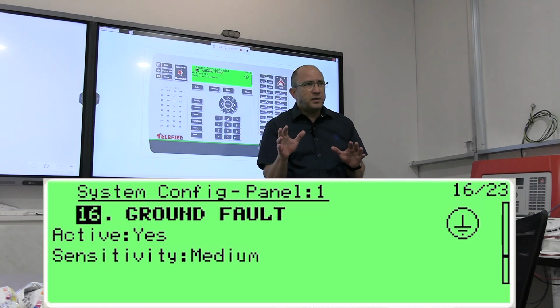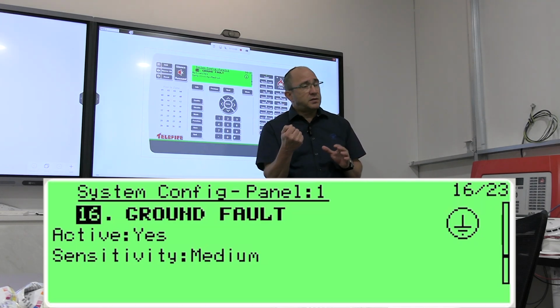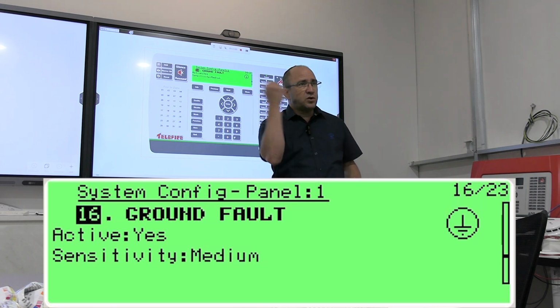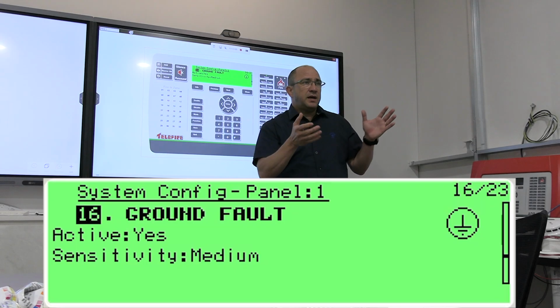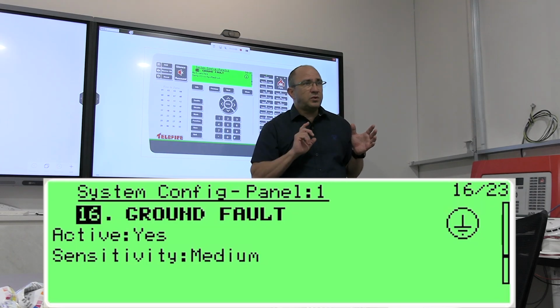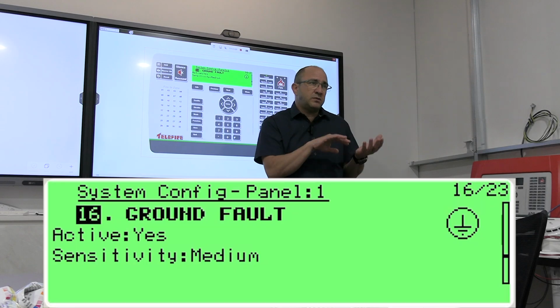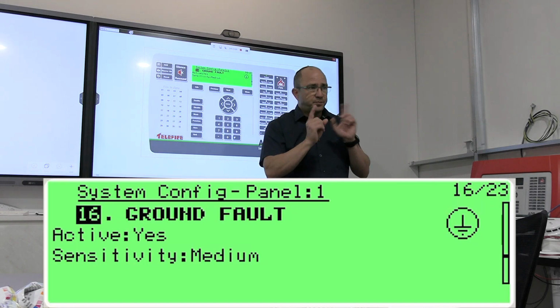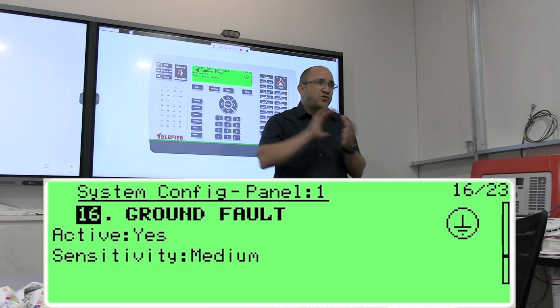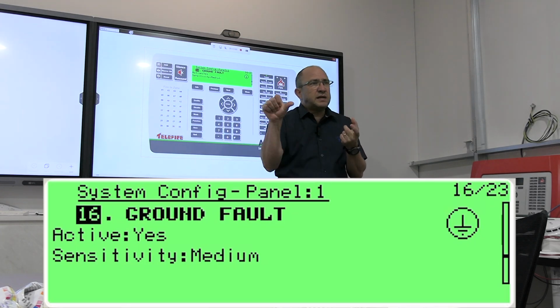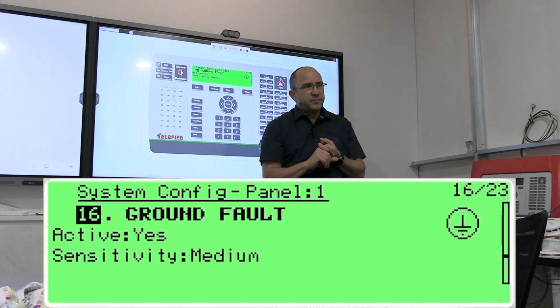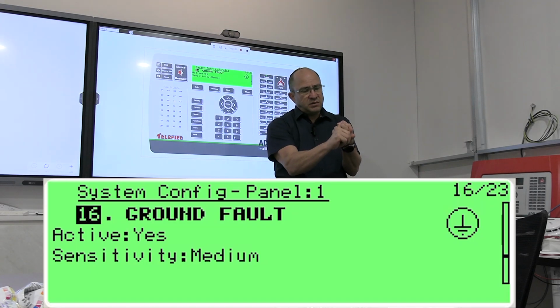After an hour, he will take a hammer, that's true, and he will break the control panel because he's a guard stuck somewhere, and you can't silence it because the problem goes in, goes out, goes in, goes out. That's usually with water. If it's a cut and dry fault, the earth is touching the minus like this, you can do silence, everything's okay. Because it doesn't go in and out, it's stuck.